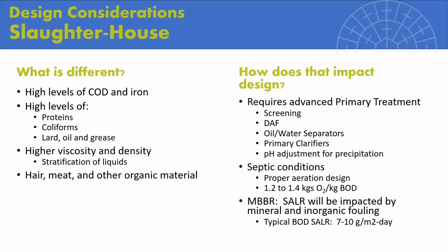But further to that, with such a high COD, a high BOD, and maybe extended hydraulic retention times, we typically need to upsize the aeration system, specifically the amount of kilograms or mass of oxygen per mass of BOD removed. In general, with aeration design, the longer retention time you have, longer solid retention, longer hydraulic retention time, the need to have a higher mass of oxygen to BOD is required.